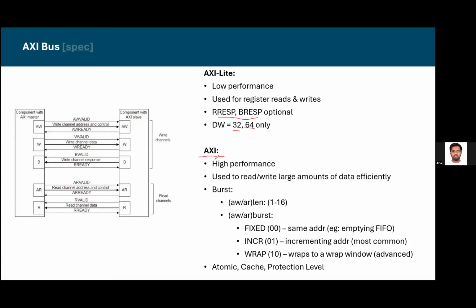You don't usually do that, but there is such a feature in AXI. Let's say you do that: you have 128 bytes in parallel, but you have told it that you are only going to use say 32 of it.